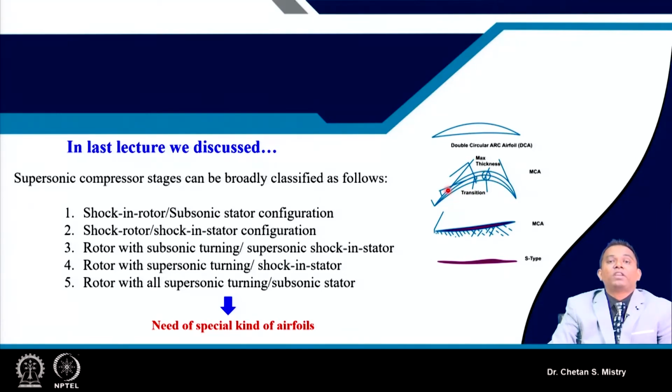The flexibility here is as per the requirement. We can change the radius or the curve of the suction surface front portion and suction surface rear portion, meaning towards the leading edge we can modify our flow passage, and towards the trailing edge also we can modify our passage.